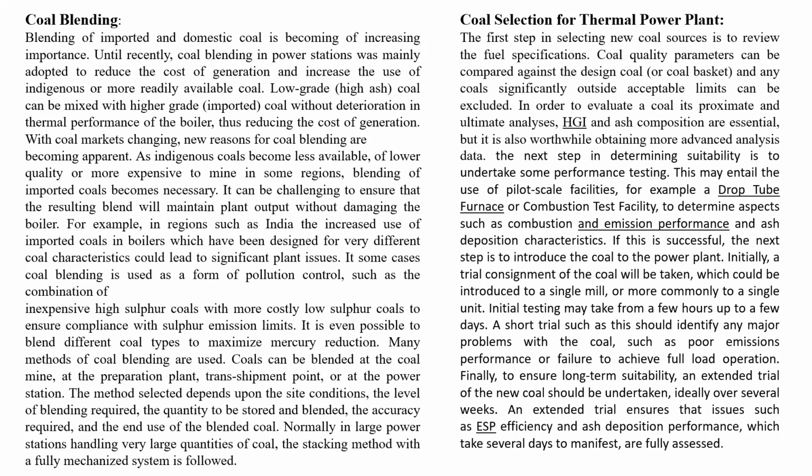As I told, blending means mixing of two grades of coals. Until recently, coal blending in power stations was mainly adopted to reduce the cost of generation and increase the use of indigenous or more readily available coal. Low grade coal can be mixed with higher grade, that is imported coal, without deterioration in the thermal performance of the boiler, thus reducing the cost of generation. With coal markets changing, new reasons for blending are becoming apparent.